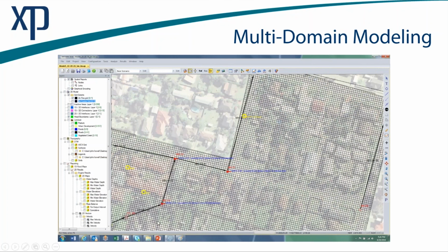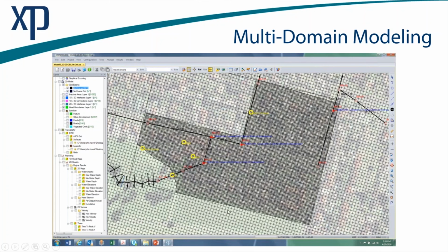Now you can see the little village area, and this is the area where I saw some flow down the streets and flow between the buildings. I can actually create a more finely gridded mesh that's a subset of the larger mesh to capture the characteristics of the flow in that area much more accurately. That mesh is then embedded inside the more coarse mesh.